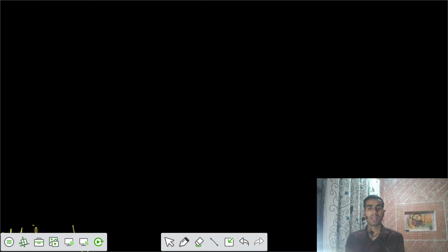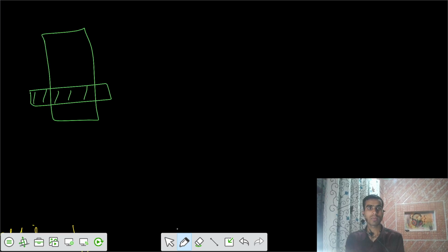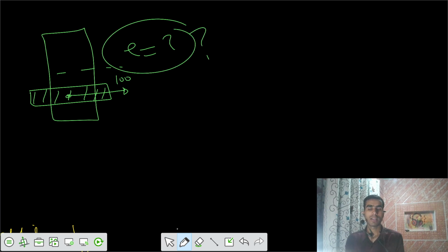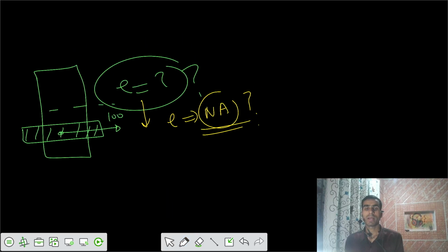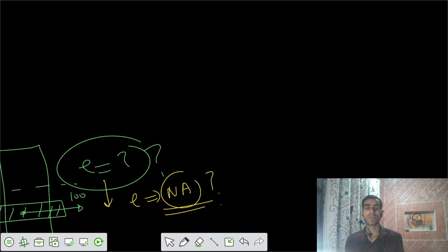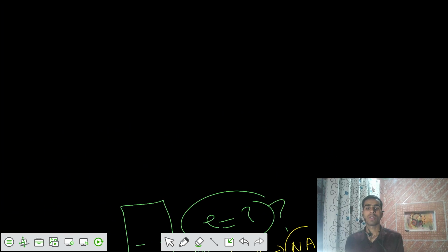Now you have this area. Is the eccentricity at some value of 100? No. Your eccentricity is now going to change. Can you tell me why? For the calculations of this equivalent area, eccentricity is measured from the neutral axis. But your neutral axis has changed by 0.867 millimeters, so your value of e is also going to change.